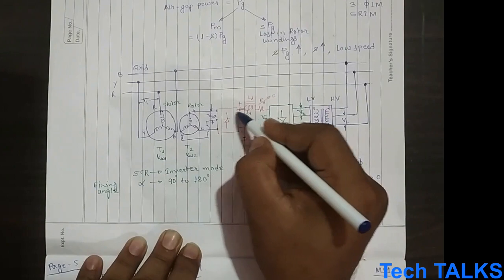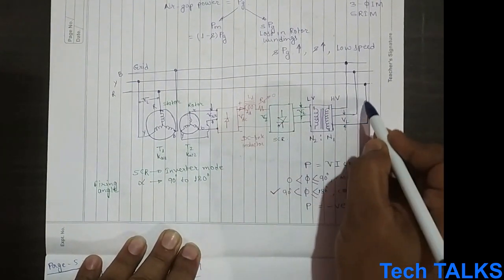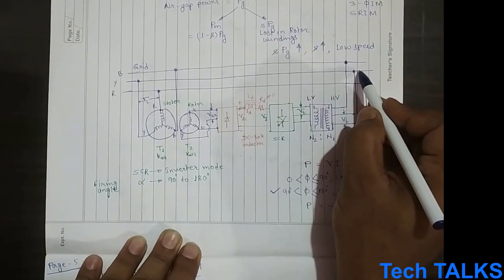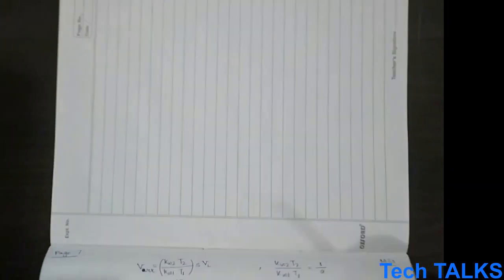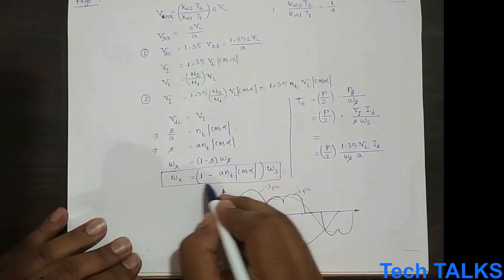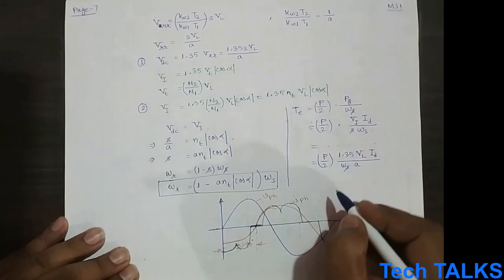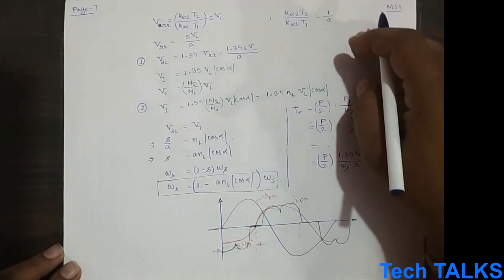So the power that was lost over here, that is SPG, we are actually feeding to here, but we are also controlling the speed of the motor at the same time. So this is effectively the slip power recovery scheme. I will be ending my session now. Thank you. We will meet again in the next session.